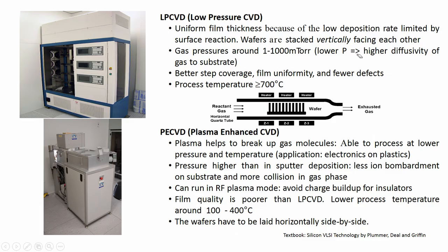Now, what is another type? PECVD. So, the system will look like this. The PECVD system is like this, right. This is the chamber in which the reactions will occur, and you can see here the plasma generated. Here you can load the substrate. You can lift it, you can put the wafer, and the wafer will go in this particular direction.